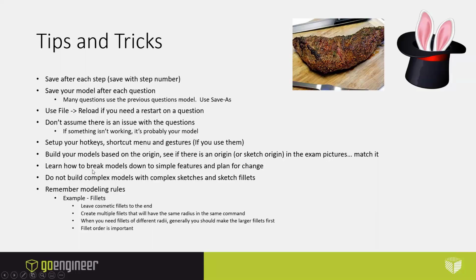Learn how to break your models down to simple features and plan for changes. Don't build your complex models with complex sketches. And this guy right here, I cannot stress enough, don't put sketch fillets in your sketches. There are specific cases where you want to do that, but I'm going to say overall, sketch fillets, bad idea. Create your fillets as features.